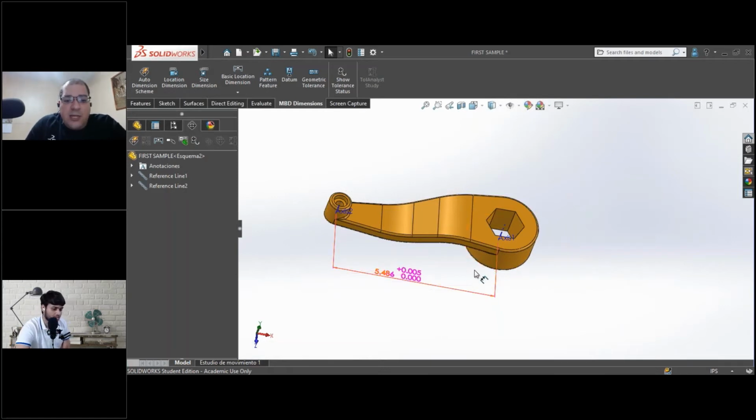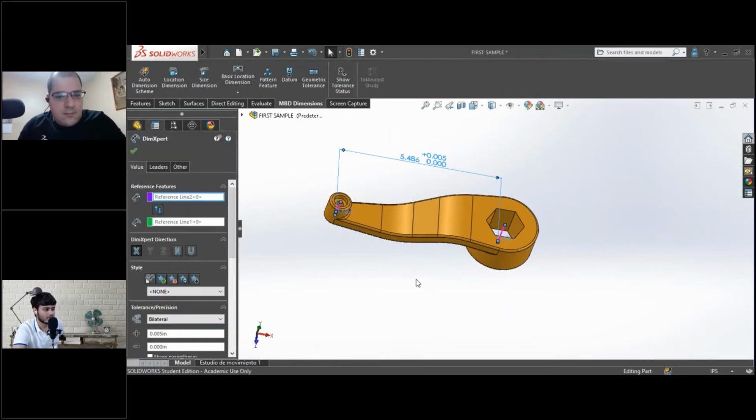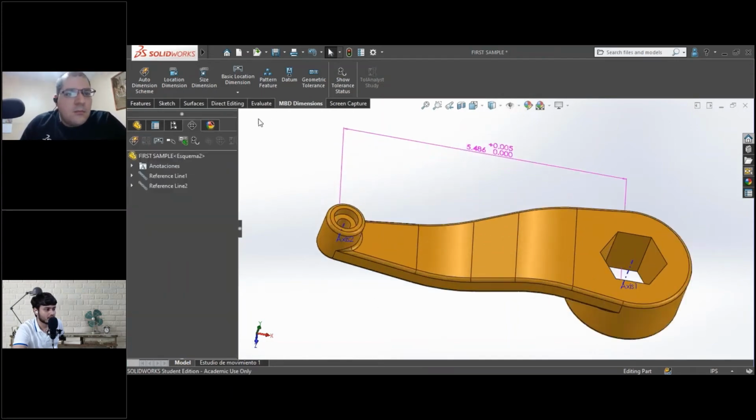So as you can see, we can place all the dimensioning, but it will look really saturated and not really needed at the end of the day for manufacturing. What we really need is the tolerancing specification for the part, so the production team really knows where this kind of dimensioning is needed. Other notes that we may need are, for example, the size of this counterbore.